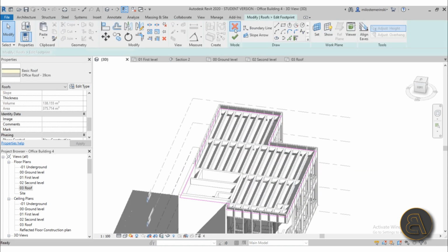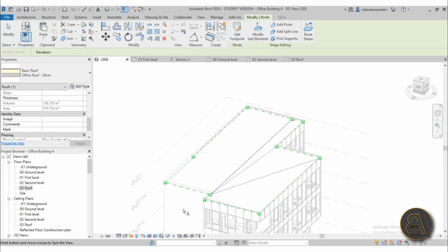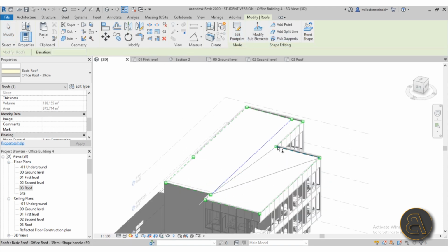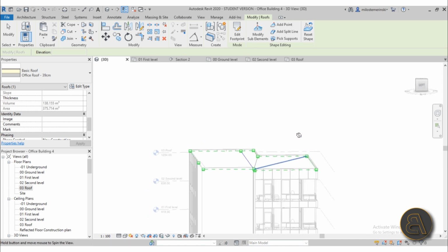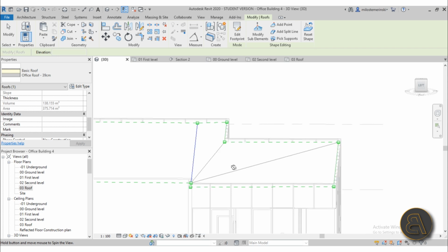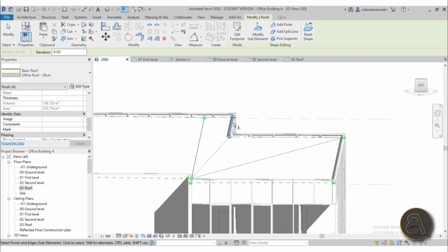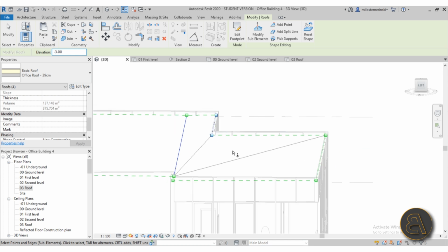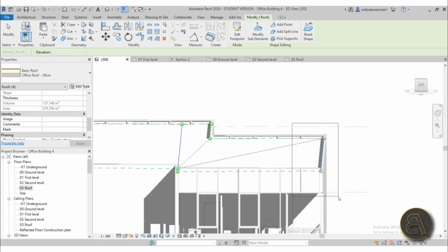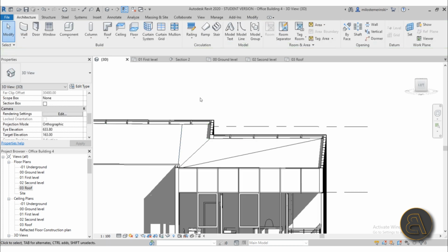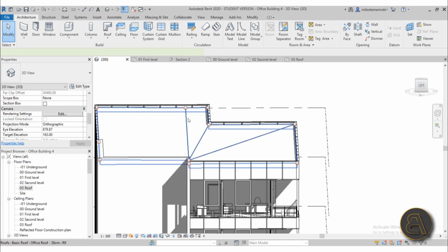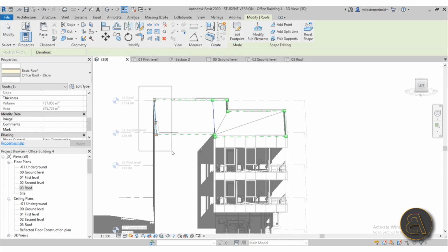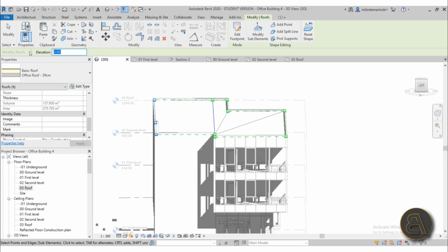That's just because here, if I go into 3D, what Revit does is basically it sloped this whole thing. Just go to modify sub elements. It sloped from here and then up to here, and then it stopped, and that's why it looks weird. So what you can do is perhaps select these two or this whole thing and give it an elevation of minus, I don't know, like minus 3 centimeters. There we go. And then this whole thing can be at like 1 centimeter height. Okay, I think this should look a bit better now. Let's go to modify sub elements again, and let's just bring this all up to like +1.